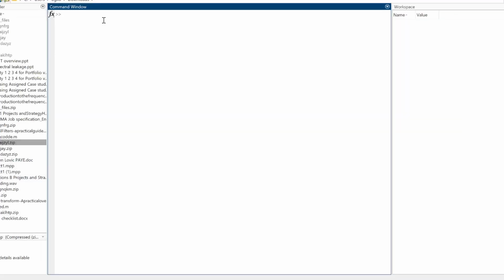So first of all, we have to load in the voice recording we made. So we have input and the FS, which is our sampling rate, and we use the audioread function to load this in. The audioread, and then we use our name of the recording, which is just recording.wav. Now we have an FS and an IP value, and now I can just play this back to see if it works, using our sampling rate, which is 44,100.